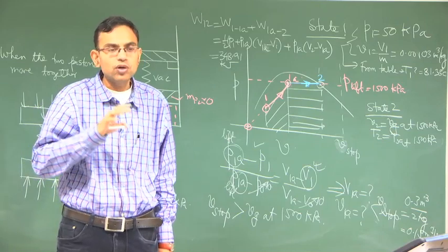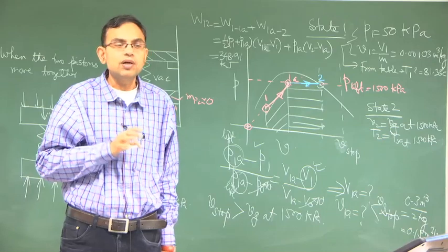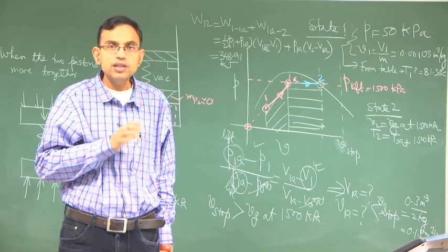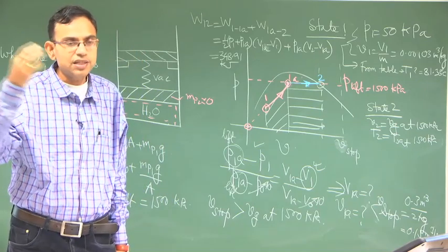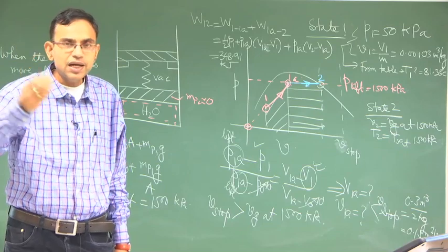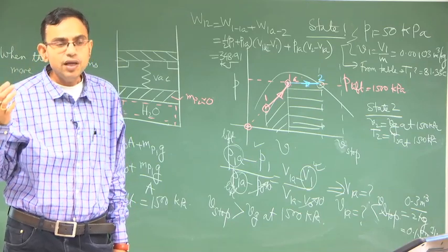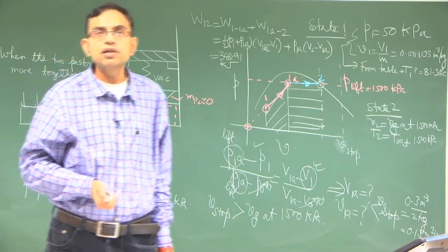So, again the problems which we have worked today, we wanted to illustrate through this that by visualizing the problem through a proper PV diagram, it is very convenient to calculate the work done. So, instead of just hypothetically trying based on the initial state and the final state, you draw the processes and then integrate PDV to get the work done. Thank you very much. We will continue in the next lecture.